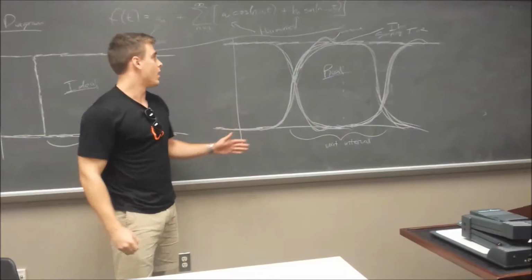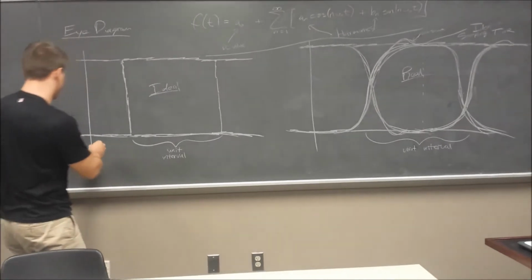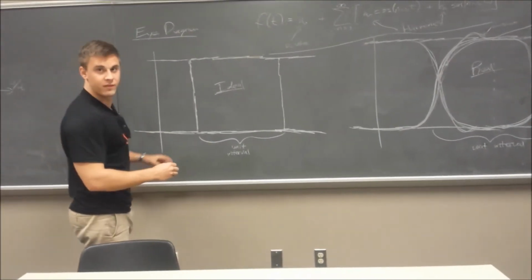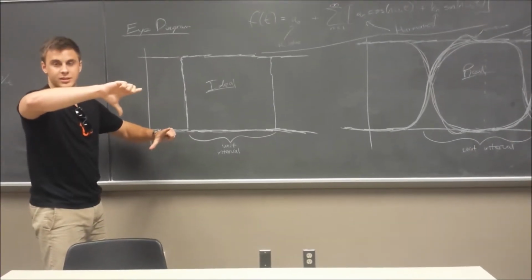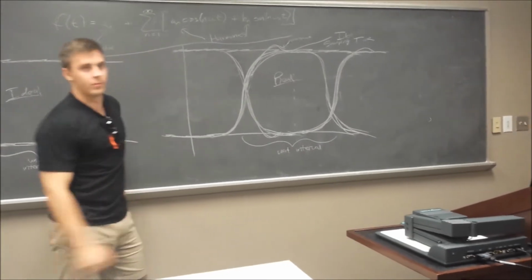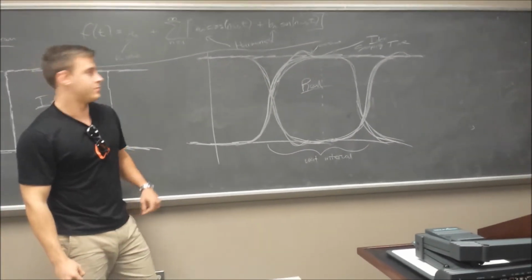can alter this. But what we're working with here is an eye diagram. This is more or less just a zoomed-in oscilloscope shot. We turn the persistence up to infinity, layering oscilloscope screenshots on top of one another. When you analyze an eye diagram, there's a lot that goes into it, but in general, you want as wide of an eye as possible.